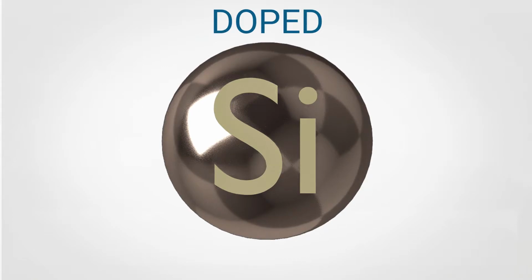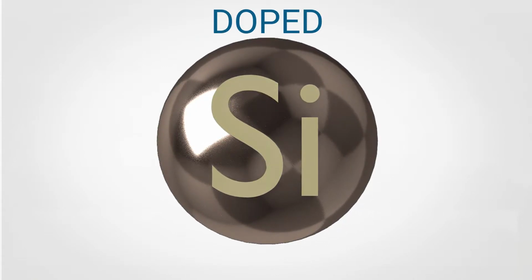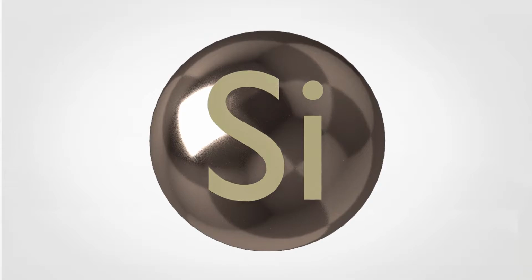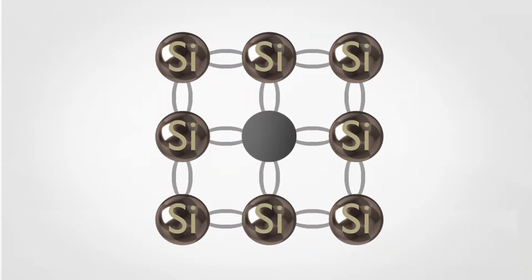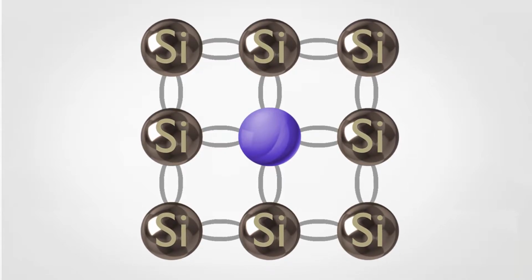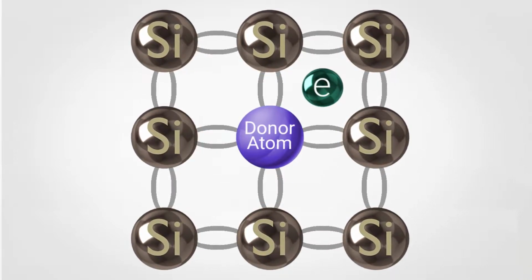By doping, we mean that the impurity inclusion is made by diffusing certain elements. In general, this is obtained by using a very small percentage of atoms spread within a silicon crystal lattice. These impurities, even in negligible amounts, change dramatically the crystal's electric behavior. These atoms are called donor atoms, since they yield electrons to the crystal lattice of silicon.